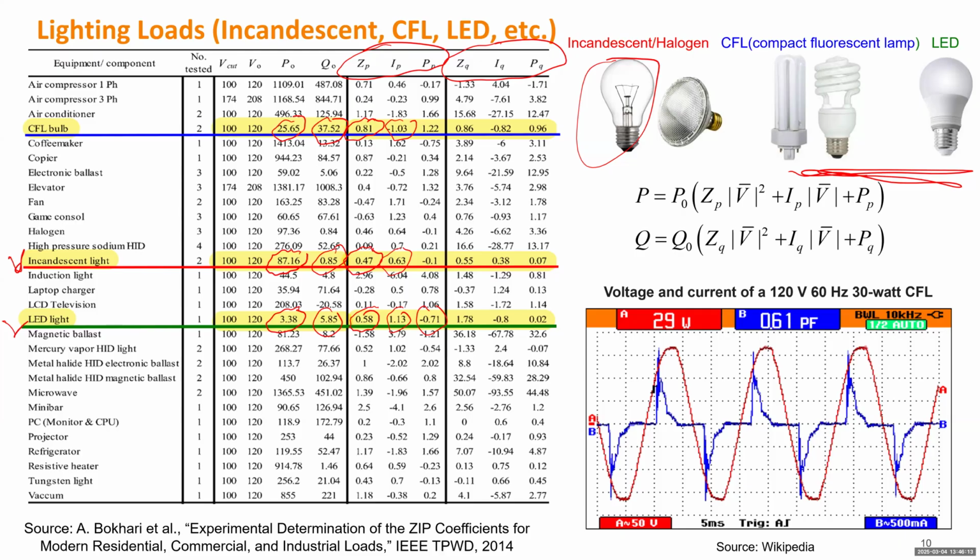To summarize, if we draw the per unit values of the current and voltage waveforms and they look almost exactly the same, that's power factor 1. If they look different, that's not power factor 1. Different means they can have a different phase or a different shape. Those energy saving lights make the current waveform very different from a sinusoid.